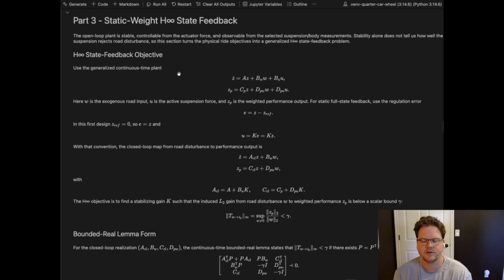We looked at the Gramians for controllability and observability, and I showed how that C, which was basically the suspension limitation from the body to the wheel, was taken, and then the other criteria was the body velocity term. That'll show up again on the observer part of this.